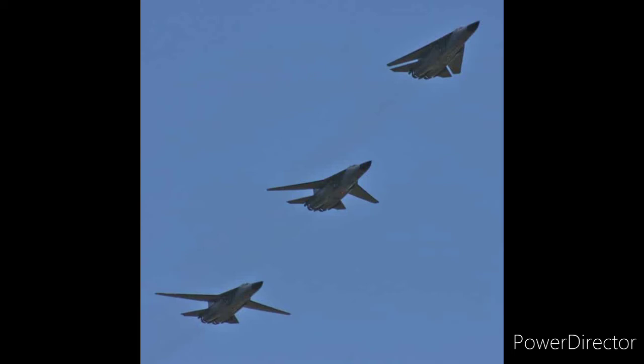Now, as you can see in the figure, the sweep of the wing is adjusted by suitable mechanisms placed inside the fuselage of the aircraft. We do this to improve the performance of the aircraft over a wide range, and mostly this is done with military aircraft. As you know, during wartime, this is designed to intercept different types of enemy planes. So naturally, this has to perform at various speed levels and various altitudes, from very high altitudes to very low altitudes.